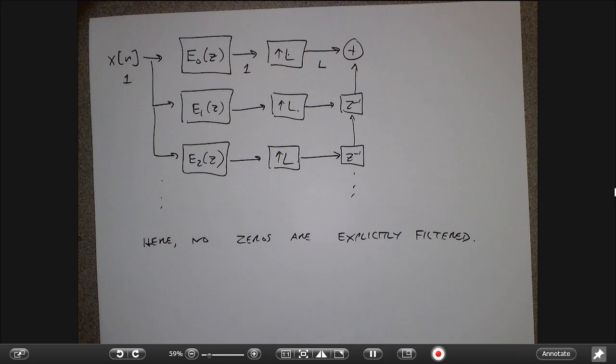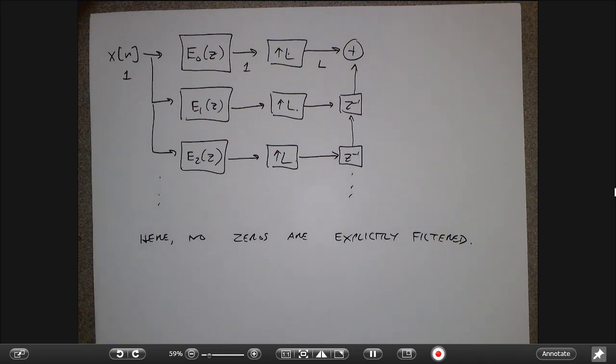So one thing that I'm not going to emphasize a lot in this class, partially because I find this kind of material a little bit tedious, is different realizations of filters, right? And that's a good project idea also, to think about what is the most efficient way to arrange DSP computations, right? Because if you're actually implementing this with parts on a board or a Simulink block structure, you want to do that set of computations in the most efficient way that you can, right? And so this polyphase decomposition is one example of a way to squeeze unnecessary computations out of the process.